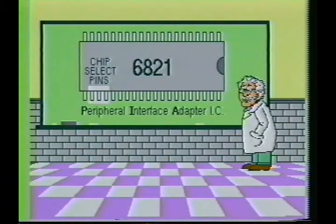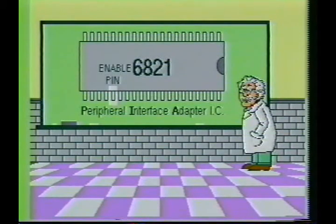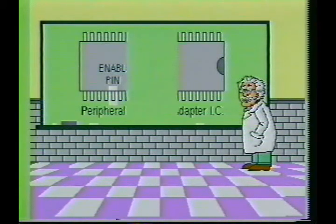This IC may be addressed through three chip select pins, CS0, CS1, and CS2. The inputs and outputs of this device are typically held at a high impedance state. Only when the chip is addressed and a high is placed on the enable input pin does the CPU actually see this device.